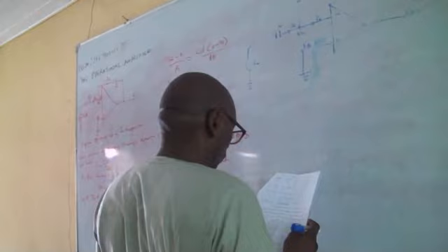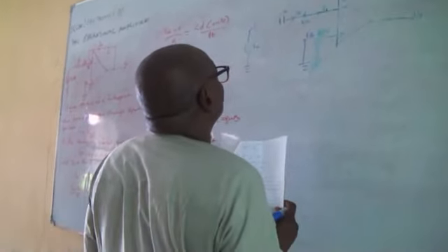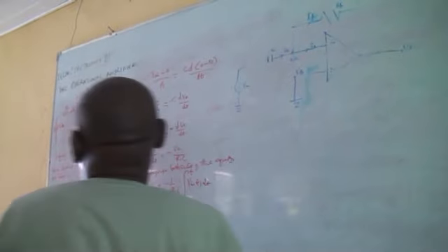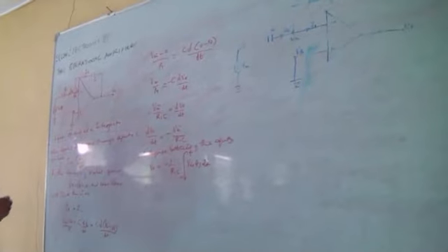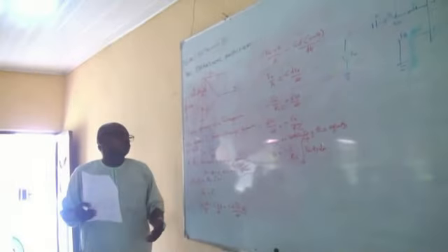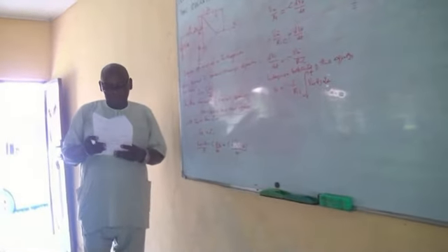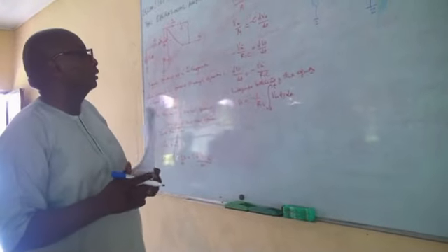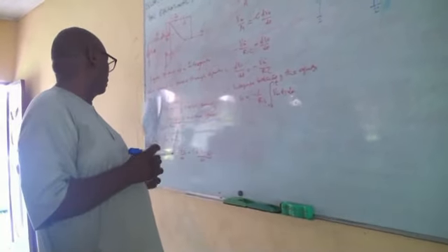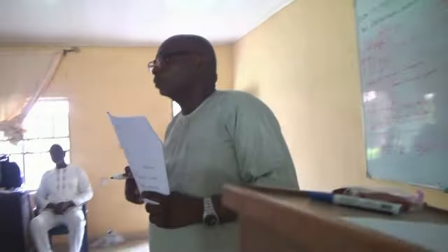Okay. This is the diagram we have, and already I've shown you the equation that's derived when current passes through a capacitor, right? Which is IC equals C dV over dt, right? Now, we have been discussing the concept of virtual ground here. These are the key things, and the effect of high input impedance on the input current to the differentiator.